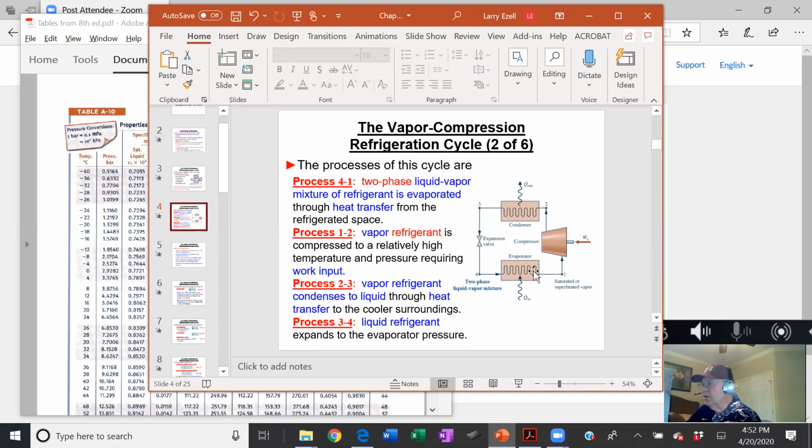Let's take the cooling mode. In the cooling mode, which is shown here, the evaporator is inside the house, and it's providing some nice cool coils to blow air across. Now I want to heat. What do I do? Well, I don't physically go outside and bring the condenser inside and put the evaporator outside. What you do is you reverse the flow of the refrigerant. Now, instead of going counterclockwise, it's going clockwise.